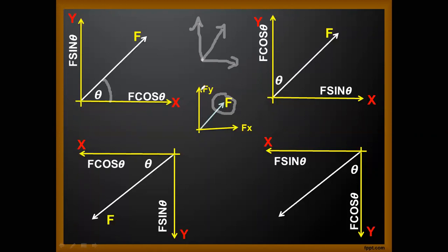Why do I want to resolve into horizontal and vertical components? Because for calculation of summation of horizontal and vertical, I want to take the forces which will be along the x direction or along the y direction. So that is the reason we have to resolve the forces. Now let me come here.